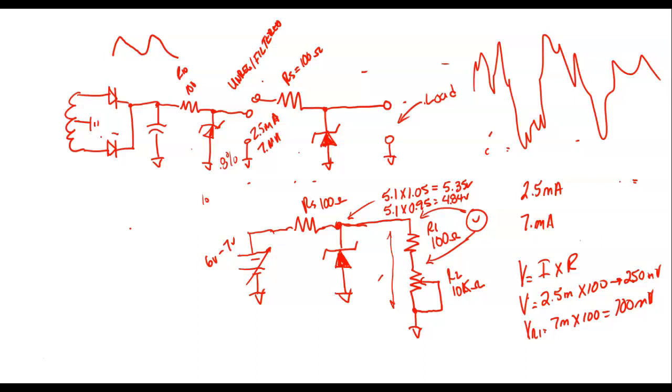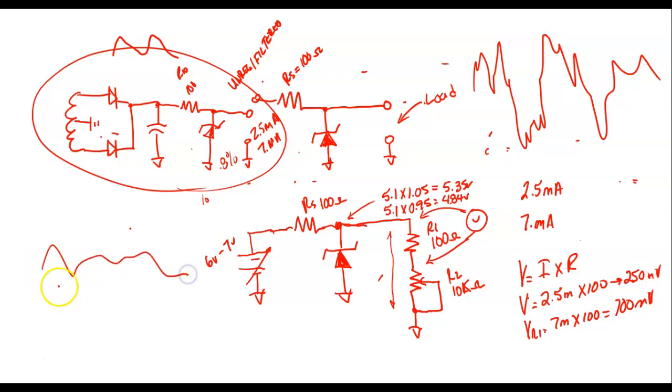I think the only thing that kind of confused everybody was that the rheostat changed that current. Yeah, and that's what we're doing. So we're simulating a change in load. But instead of this being arbitrary, I wanted to prove my design before I built my circuit. So I set up a static situation where I could actually put 7 volts in, or put 6 volts in, instead of the voltage over here on the input doing this. See? So this thing should regulate. If the maximum is 7, the minimum is 6. This guy should regulate even though the input is all over the place between 7 and 6, right?